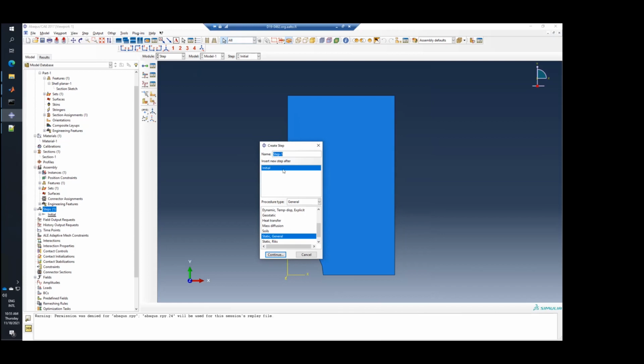And here, to save the calculation time. Normally when you do a unit cell tension in Abaqus, you can use Static, General to do your simulation or calculation. But here, to save time, we will choose another one. So try to find this one, Dynamic, Explicit.